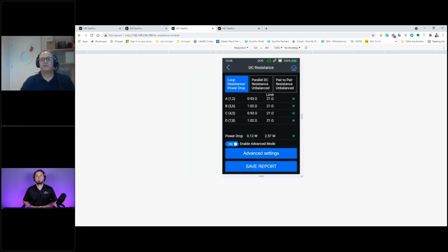Okay, this is the complete resistance of the twisted pair. The parallel one is taking the 2 wires in parallel. They are reflecting a different resistance that the wire is seeing. Why is it important? When you're driving the signal, you have a return path that must go through the lines. Otherwise, you will not be able to transmit anything.